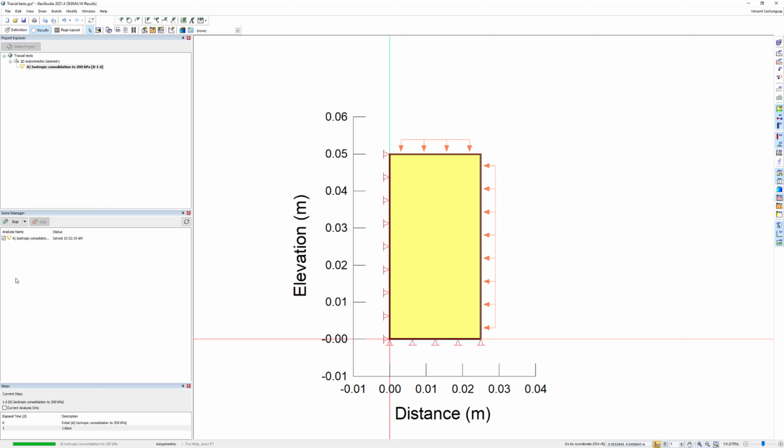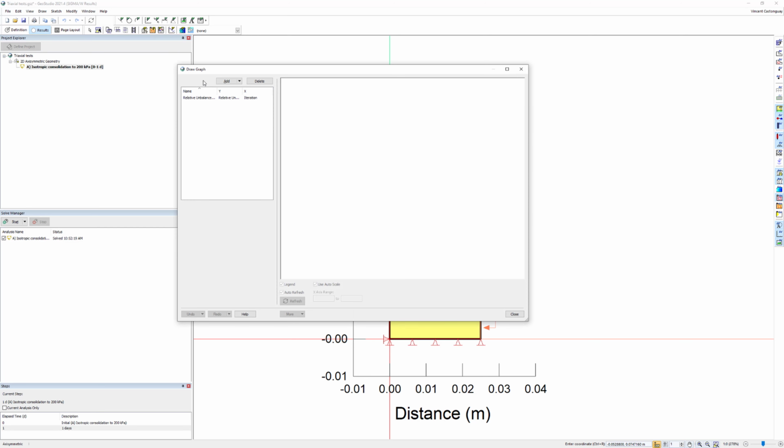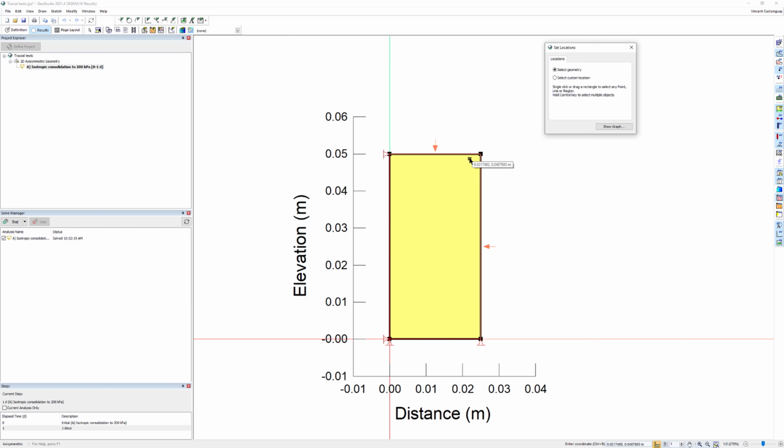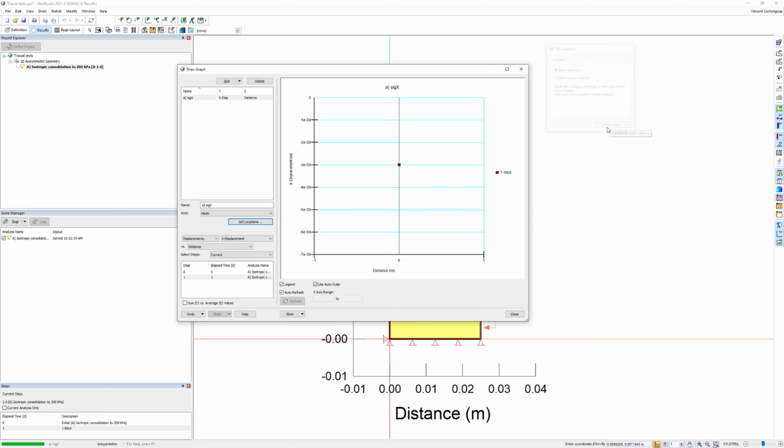There are many ways to do this. To me, the simplest method is to plot the information relevant to the simulation I am performing. In the case of this consolidation step, I will plot the horizontal and vertical stresses to confirm they were both initiated to 200 kPa. When creating the plots, I can select any node in the domain since we expect the results to be homogeneous.